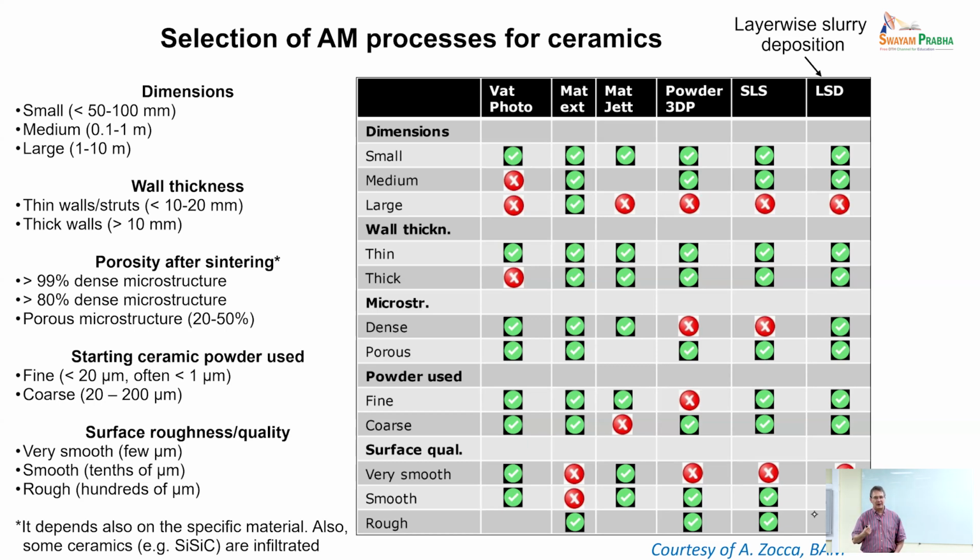Then the issue becomes how you consolidate that. And he came up with this idea of using a laser to selectively dry, and you also have some organics in the system that bind the particles. So he uses a laser to inscribe the liquid layer. And then once he has finished processing the part, he has a component that has been built using fine particles, and this can be sintered to full density. So this is another technology that has been added to this slide, because this slide was kindly provided to me by a co-worker at BAM in Berlin.